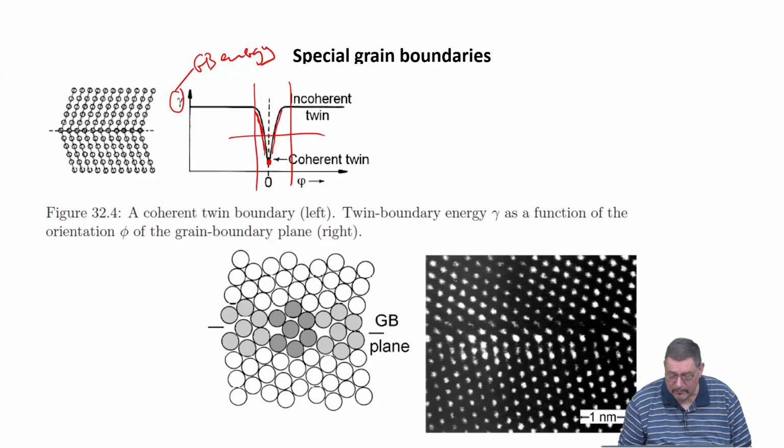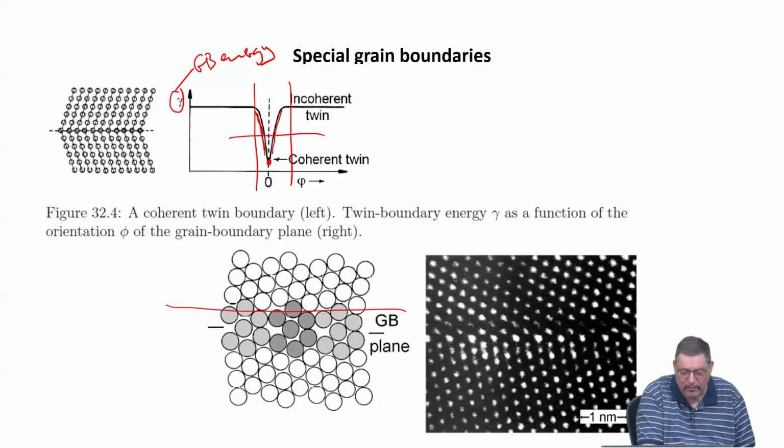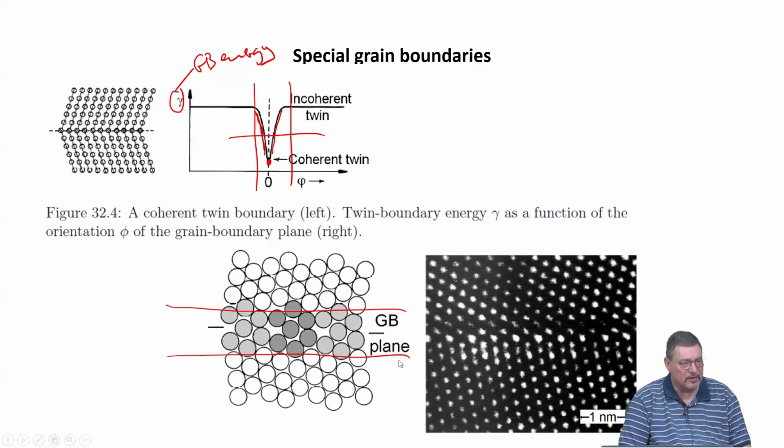Yeah, and still you see that in real materials, you always have to identify a grain boundary with a certain thickness. So whenever you do Gibbs thermodynamics, you know that you describe interfaces with a mathematical plane, the Gibbs dividing plane, right? So you project the excess quantities of the volume, which we call grain boundary, onto a mathematical plane.